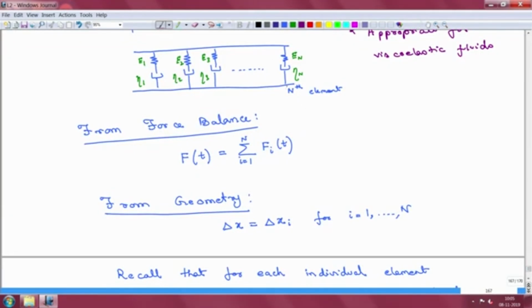One thing you could do is take, for example, the last or any of the dashpots and make this quantity tend to infinity. Okay. So, if I take the last dashpot and I make the viscosity there tend to infinity, basically what we have effectively is a spring. Okay. So, all of the deformations will be taken by the spring and it will be determined from there, right.